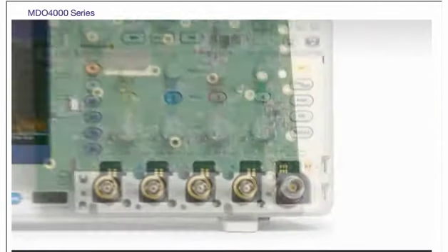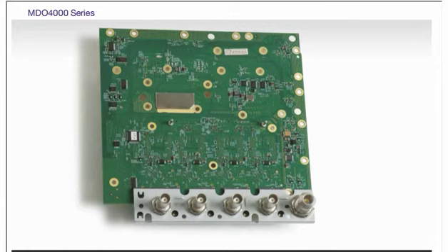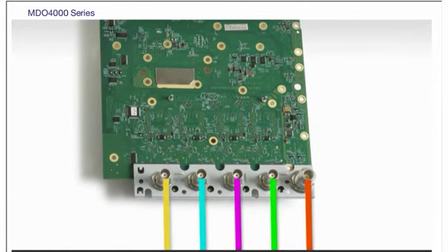The real power of the MDO4000 comes from its universal trigger and acquisition system. Because all channels are fully integrated, you can trigger on any of your signals and the scope will capture all channels simultaneously. As a result, all signals are time-correlated for accurate analysis.